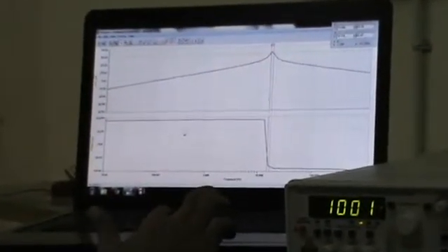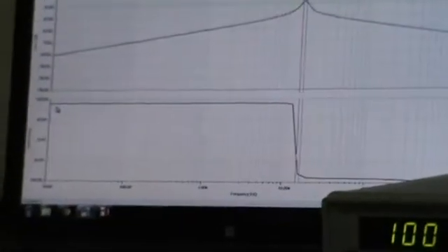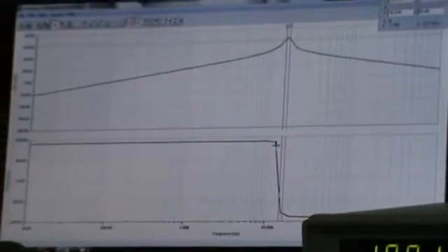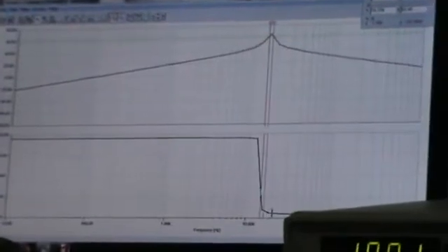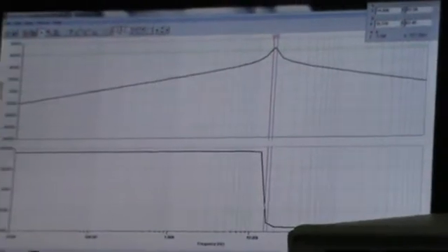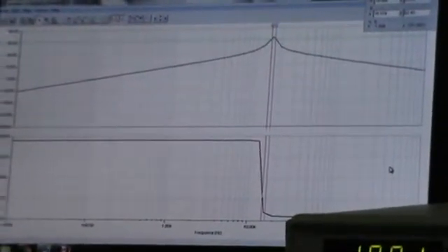We also have got the phase response here. Initially, from 1 kHz of frequency, the phase remains the same. The phase difference between the input and the output remains the same at around 90 degrees. And reaching around 11 kHz, the phase suddenly drops down to around minus 90 degrees, and then as we increase the frequency, the phase decreases more, or it increases in the negative domain. So this was the frequency and the phase response as we obtained on TINA software.